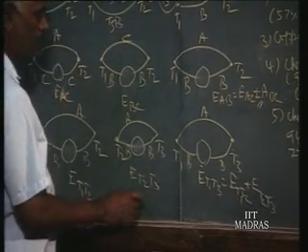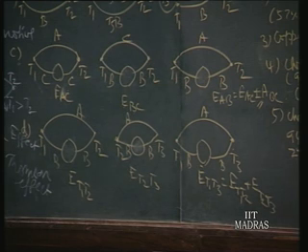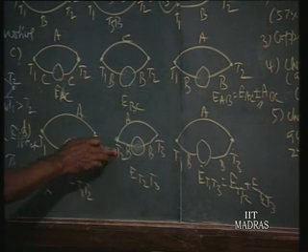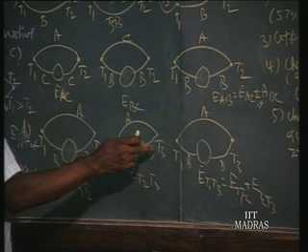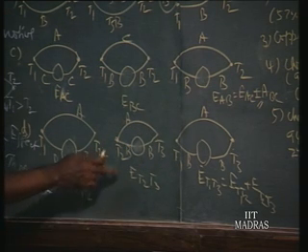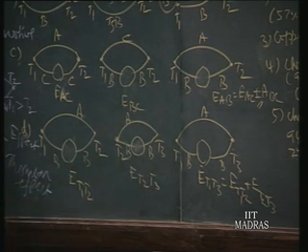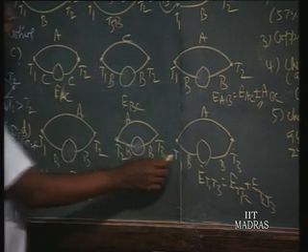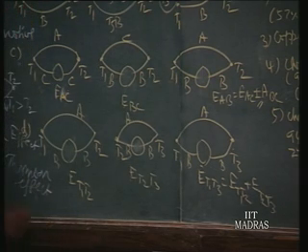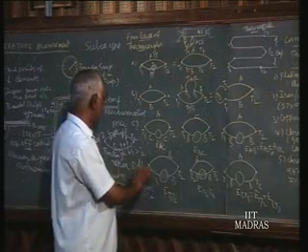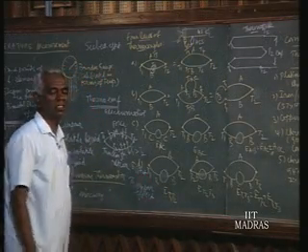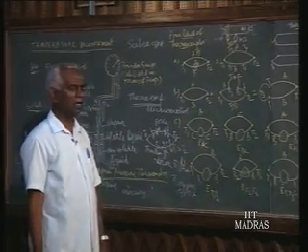Mostly you will find your T2 is the atmospheric temperature. So we measure with atmospheric temperature as the cold junction, and T3 is the higher temperature. That voltage we measure, and from the chart for the A and B material combination, you can get the voltage from T1 to T2. Add these two voltages, then you know the total EMF developed for a temperature difference of T1 and T3. So corresponding to that, you can find out the temperature T3. That is how the fourth law is made use of: the cold junction temperature is not always 0 degrees centigrade, it can be any other temperature.